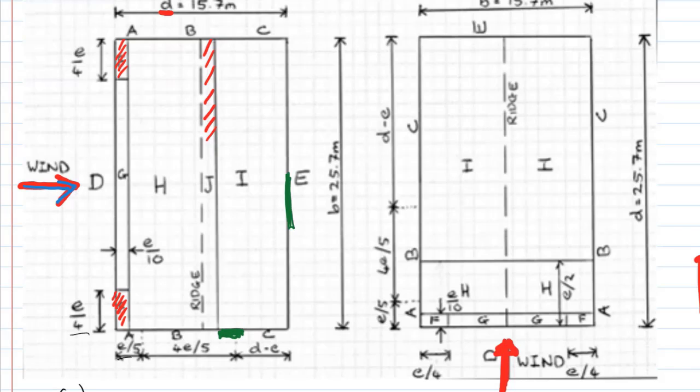And then also we have some leakages. There's about a 30mm gap between the sheeting and the side walls, and that gap in reality could be all over the show. It depends on the quality of installation, on flashing details, on all sorts of things. But now we need to work out the internal pressure coefficient, so how pressurized is this inside.